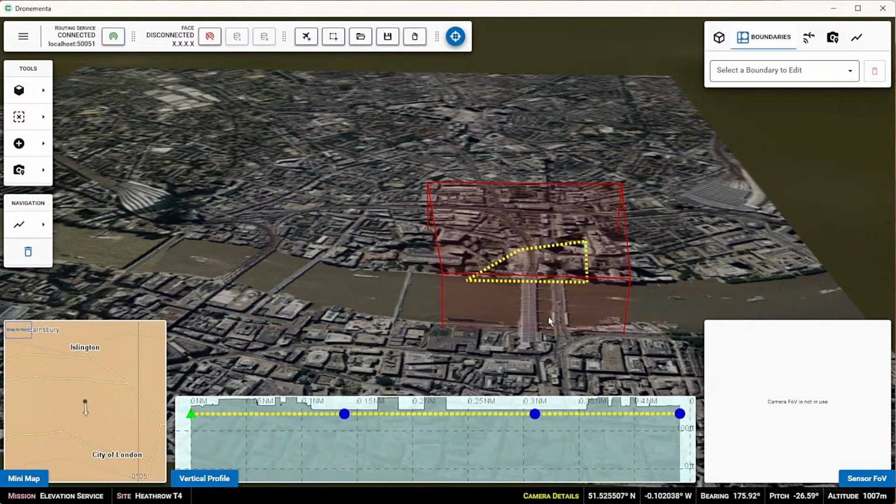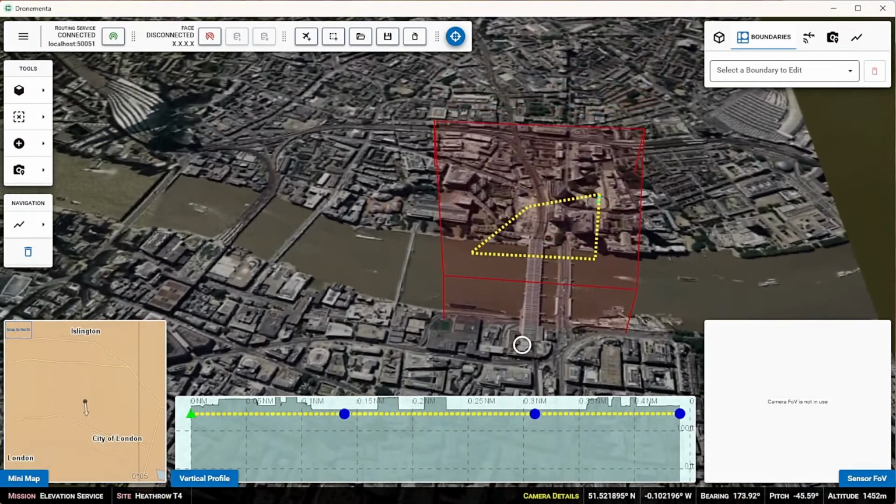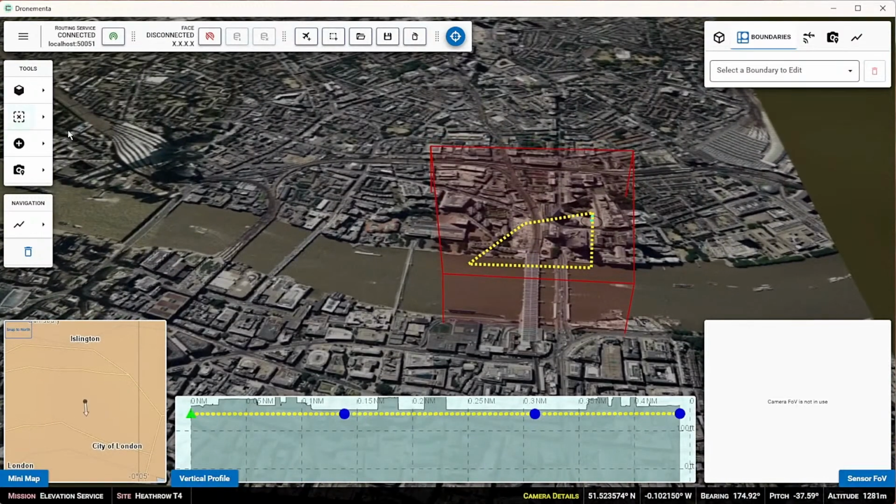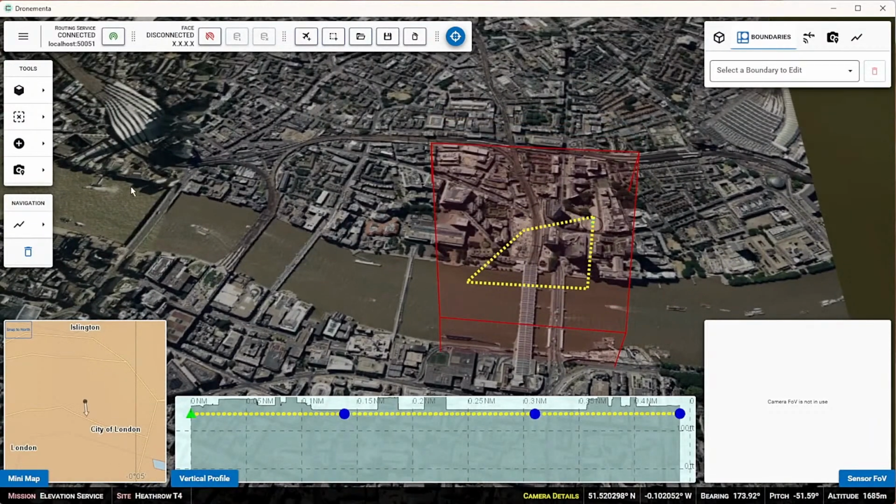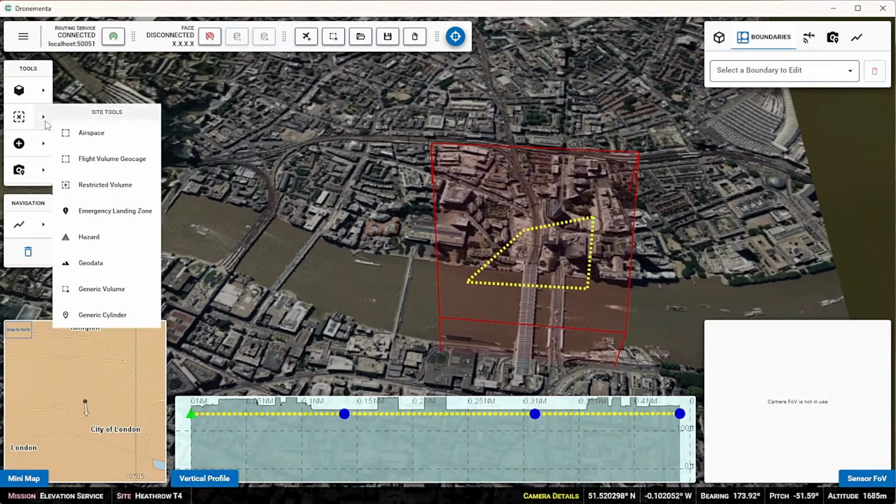So that's really useful for things like return to home altitudes. If you lose communications inside your operating area, you'll want to make sure that the drone does something safe. And if the drone is programmed to go back home, you might want to ascend to a certain altitude. This way you can ensure that you'll clear all of the buildings in that area. Obviously you can't really see that that's a relevant altitude, but there are some other API calls in this elevation service that can be used.